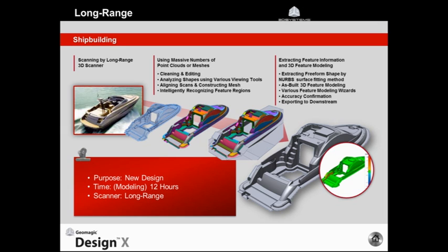Then some boat deck design, done in 12 hours with all those features and all information. You can see in the middle of the screen the boat is segmented into several colored regions. Those colored regions are basically areas with equal or similar curvature, and based on this equal or similar curvature we can fit geometries. We can do freeforms, we can do prismatic features like cylinders, cones, spheres, torus, whatever, and we can use those and trim the features with the remaining parts to get the final model.